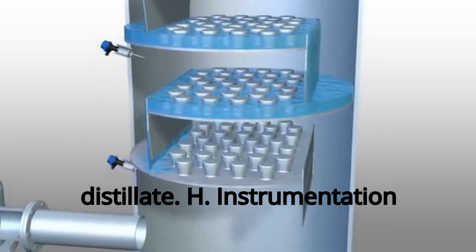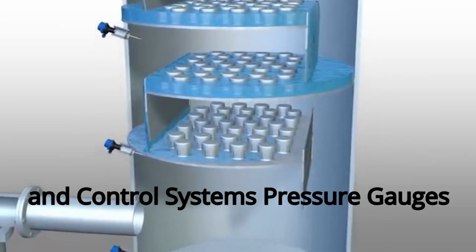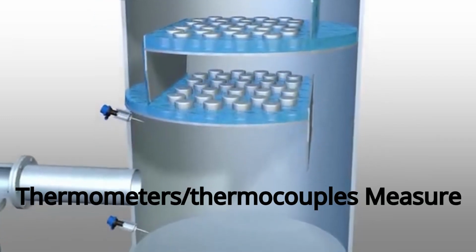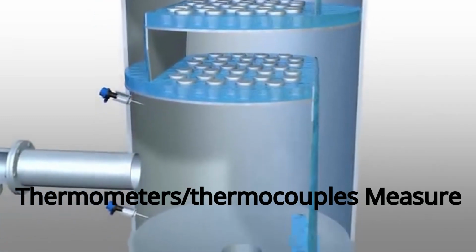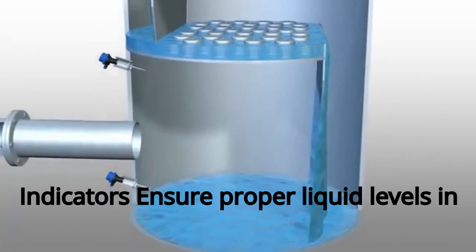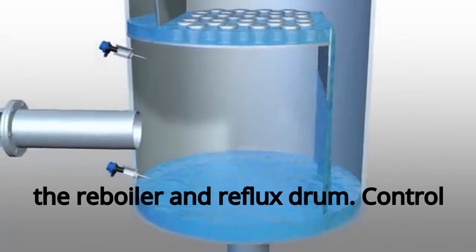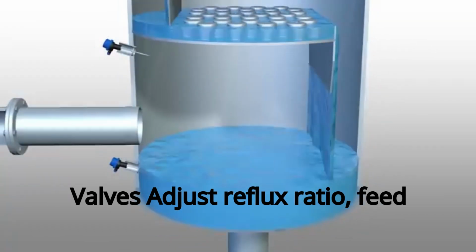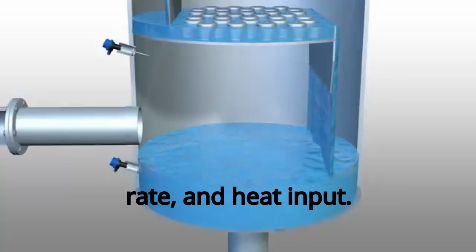H. Instrumentation and control systems. Pressure gauges, monitor internal pressure. Thermometers/thermocouples, measure temperature at different points. Level indicators, ensure proper liquid levels in the reboiler and reflux drum. Control valves, adjust reflux ratio, feed rate, and heat input.